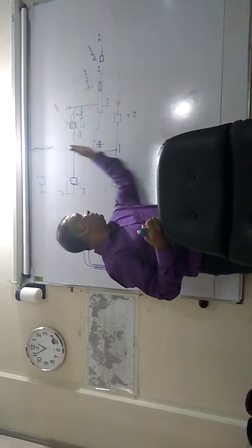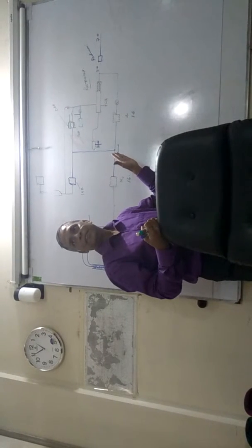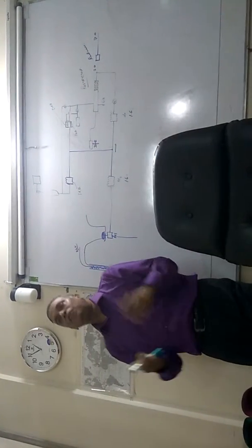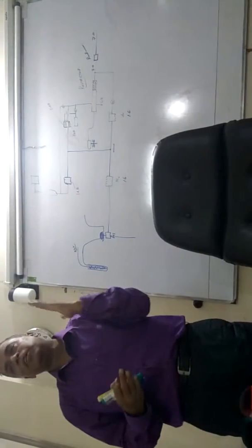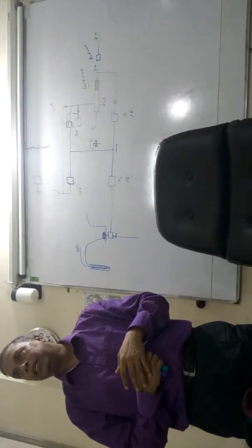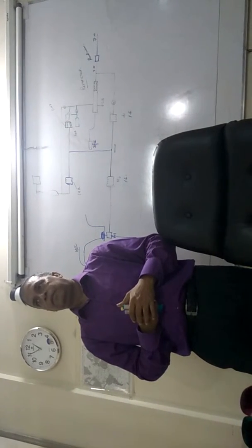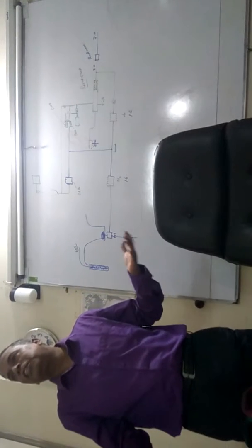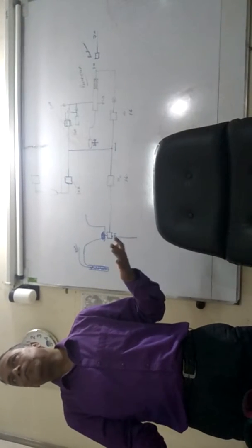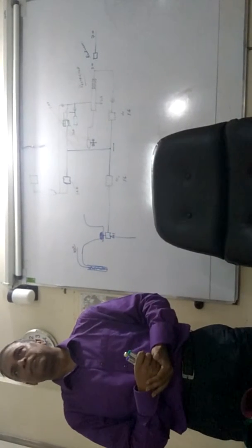When there is no difference, this is in vertical. Okay? Right? So these two, MV and DV, whenever there is a difference, then only the flapper's bottom moves either to the right or to the left. Okay? And this movement we call deviation. Alright? So what is deviation? The difference between measured value and desired value. Okay? And deviation causes the flapper's bottom to move right or left. Agreed?